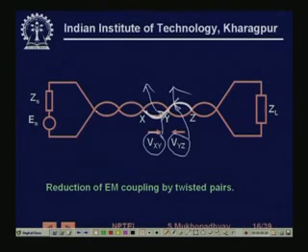So the effective EMF induced by such stray fluxes linked by this coil between these 2 points will actually be cancelled in these successive loops. So the net EMF linked from interfering sources is much reduced. First, your area itself is reduced because they are twisted, so very little flux is linked, and whatever effect it produces also gets cancelled because of twisting.